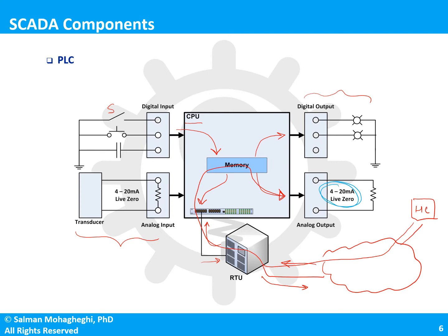You do this intentionally because if 0 volts is coded as 0 milliamps, every time you get 0 milliamps, you would assume that everything is fine, and this is just indicating a command of 0 volts, for instance. However, it is possible that you have an issue in the system. For example, one of the conductors breaks. If the conductor breaks, you're not going to have any current flowing through that conductor, so you will have 0 milliamps, which is an indication of a problem in the circuit. However, you would be interpreting that as 0 volts.